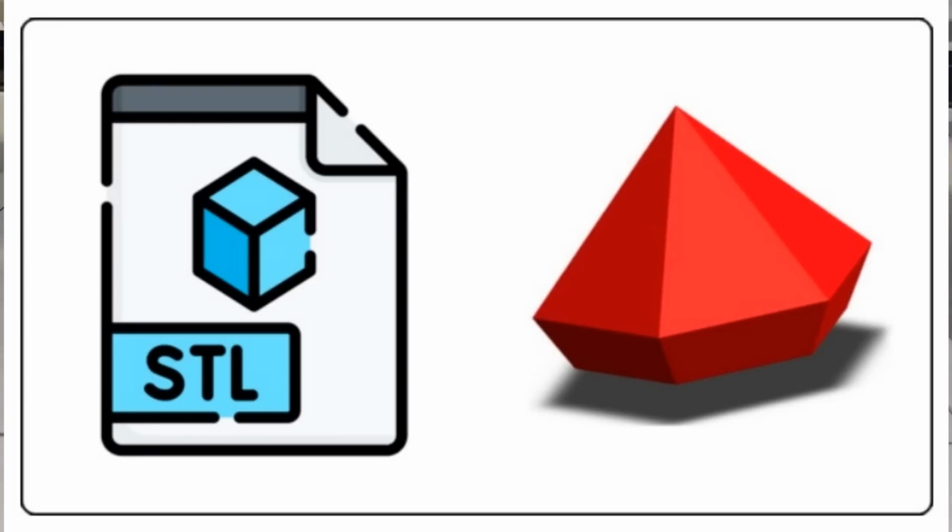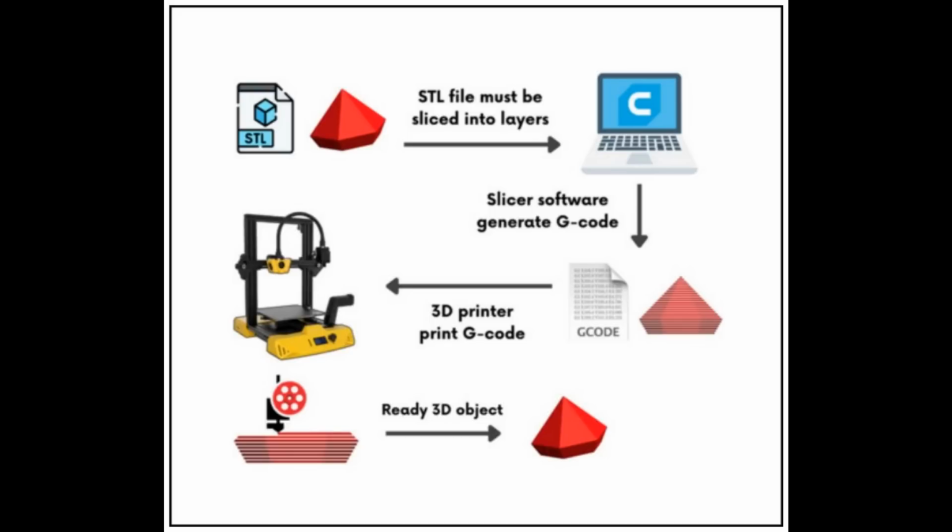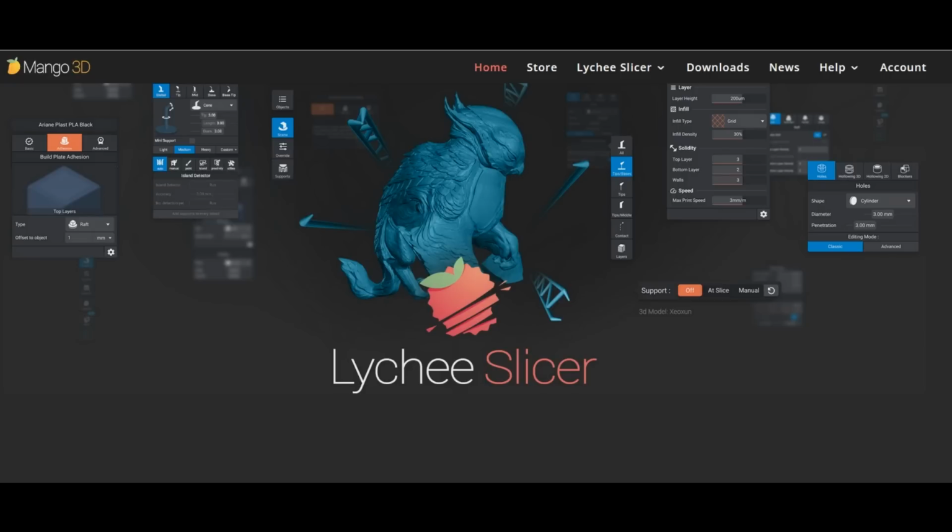The STL file is a graphic representation of the model that you've just built. The printer can't understand that. The slicer turns that into a set of commands, moving the head backward and forward, timing the extrusion of the plastic, that sort of stuff, so that a physical print can be made by commands that the physical printer understands from the STL file that you did the drawing in. That's the job of the slicer software.